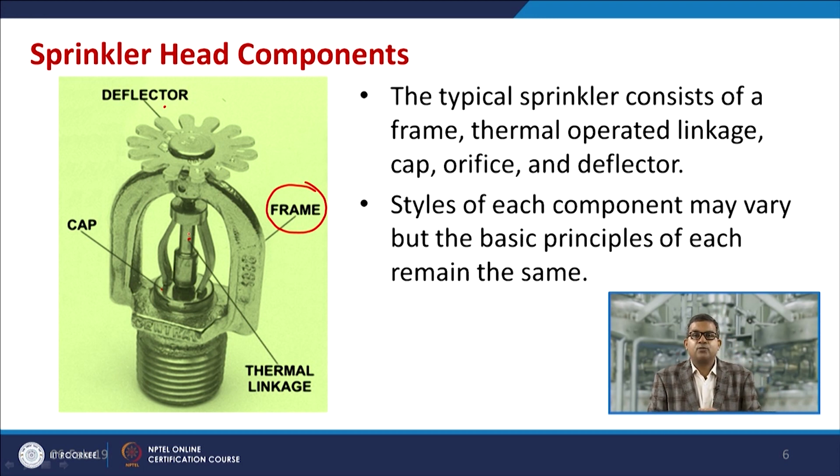First it should sense a rise in temperature, through the thermal property of the material in question, so that it can sense there is a problem and provide adequate opening for the water. The water then comes out from the cap to the deflector, and the deflector spreads the water to the problematic zone.